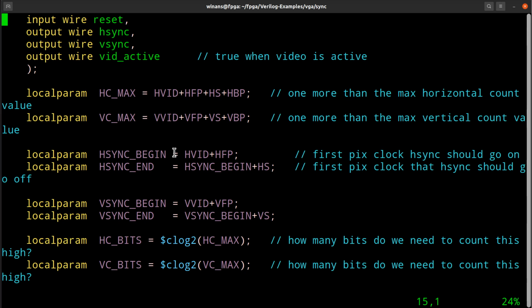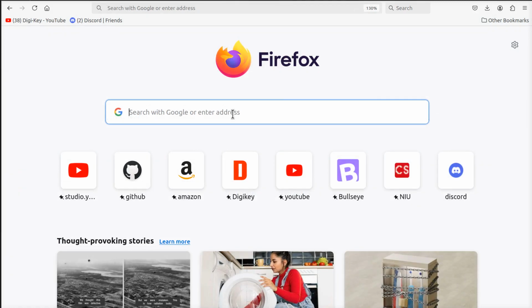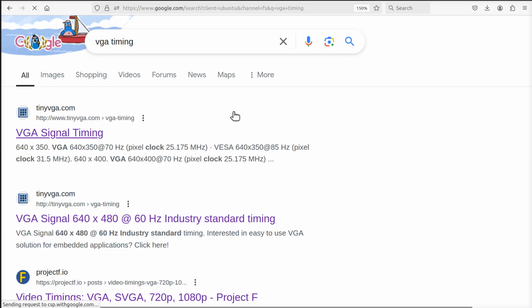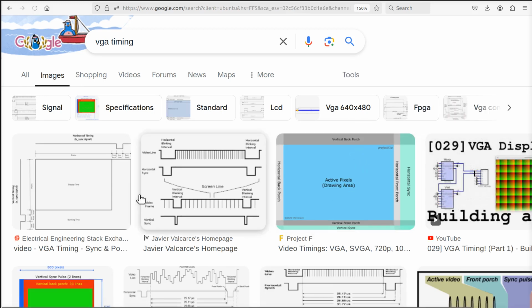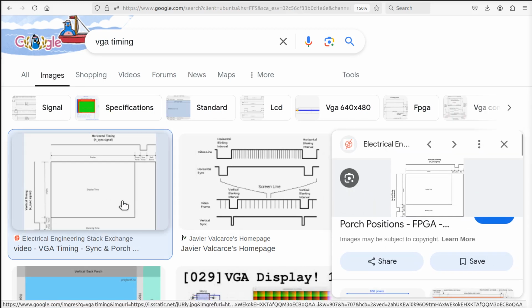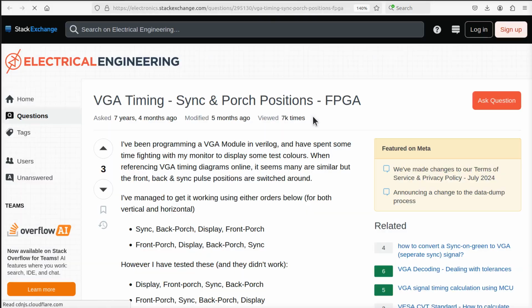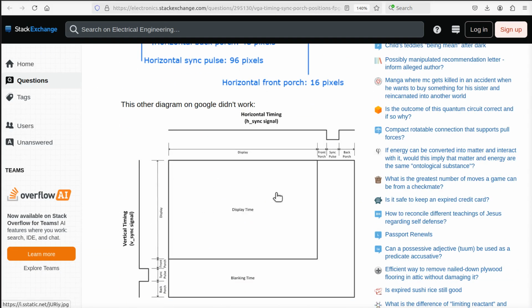You'll see that the origin of the video in this implementation, 0, 0, if this was the screen, is the pixel in the upper left corner. So for the active video, if we Googled up another diagram and clicked on images, we're going to have a system implemented like this picture here. Timing positions, yes, it'll work like this. 0, 0 is up here, and this is going to be 799 because there's 800 total pixels here. But what is it, 525, give or take, this way.